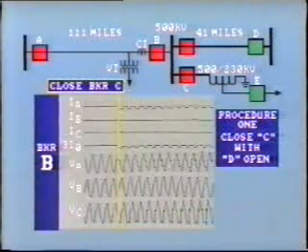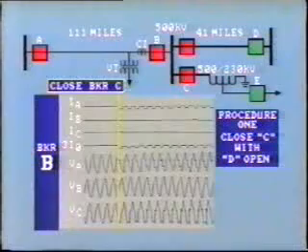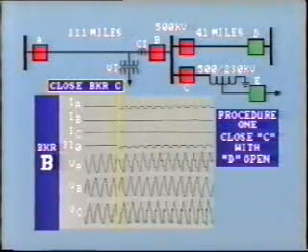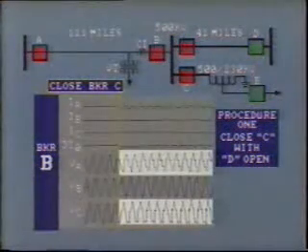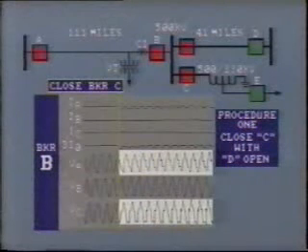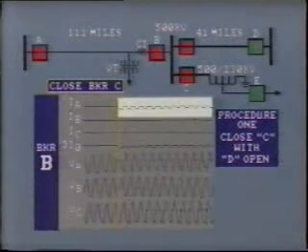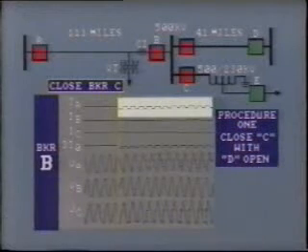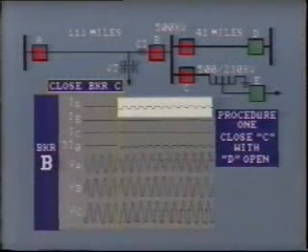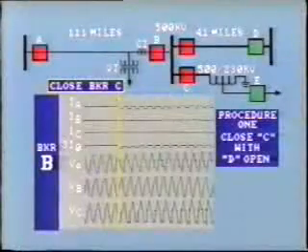Here we show the traces for procedure 1 with breaker D open. This looks quite strange. Voltage VA on the A phase shows some distortion, also VC to a lesser extent. And this current IA must represent transformer magnetizing current. Your workbook explains why only one phase is affected.